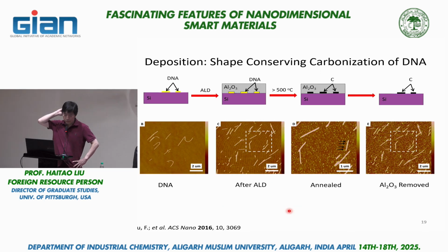All right, so another process we've been interested in is to think about how to make a conductive nanostructure. You'll recall the overall scheme we have to accomplish. One is etching. Another is some kind of deposition, and the deposition oftentimes involves conductive material because you have to create conductive wires to wire up different nanoscale electronics.